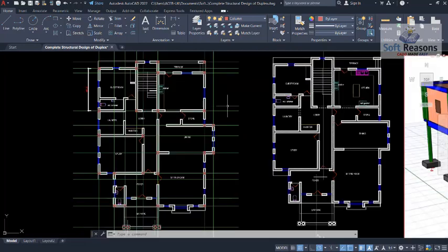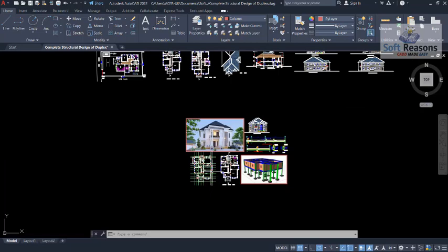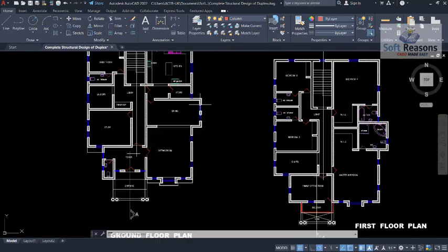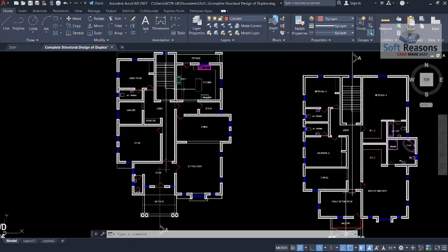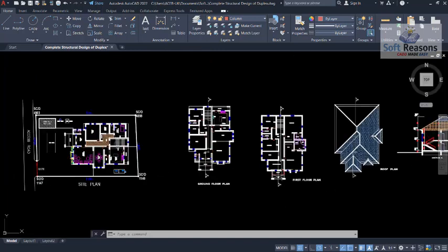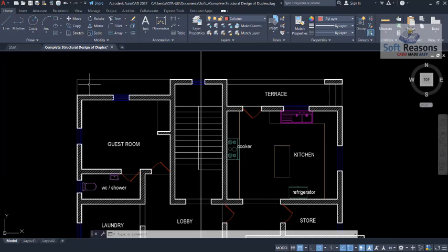Having done this, the next thing you have to do is check the architectural plans to see where you should have a cantilever or not, by superimposing the architectural plan. But since this is a simple structure of a story building, if you check very well, you will notice that we only have a cantilever here. You can see it's demarcated from these provisions.